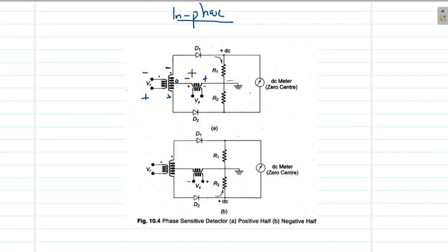That means we will have Vs plus Vr voltage in the upper half, but that voltage is reverse biasing D1, because the positive is connected to the negative of the diode 1. So this is reverse biased even when the voltage is Vs plus Vr. So let us neglect the case of the upper half during the negative half cycle.